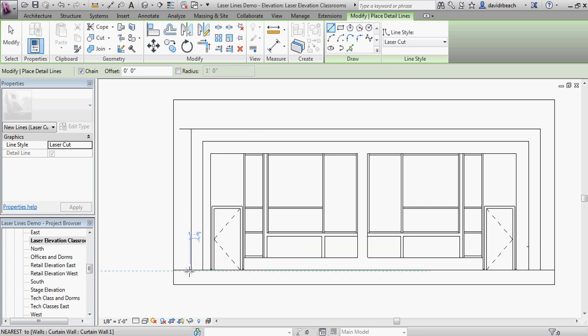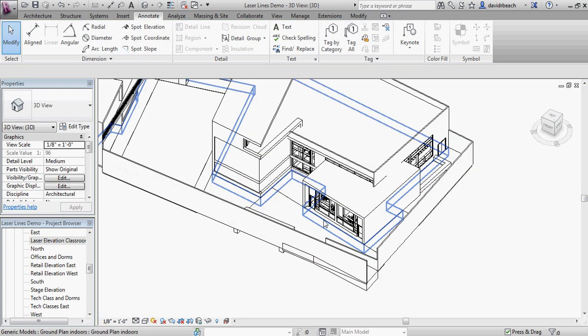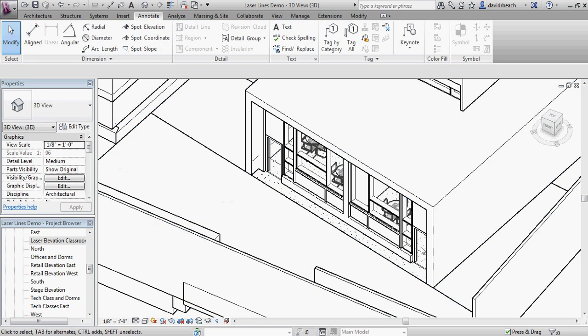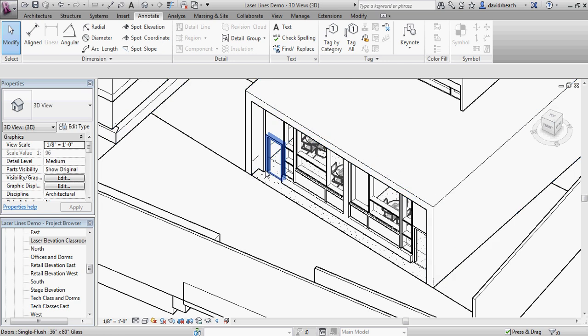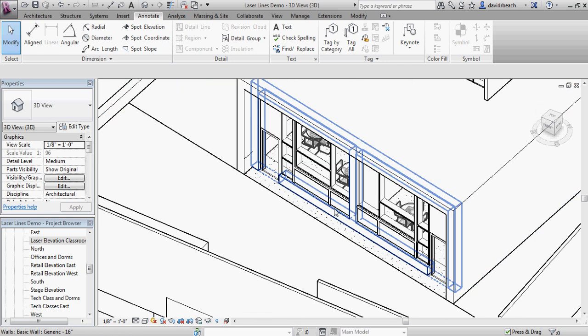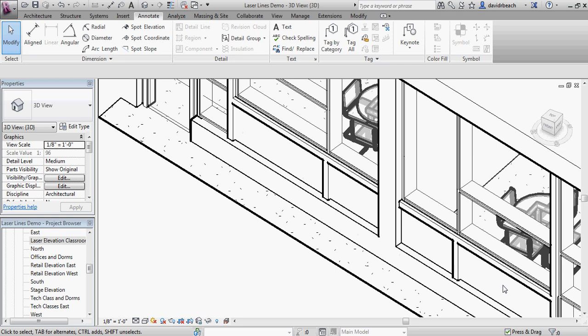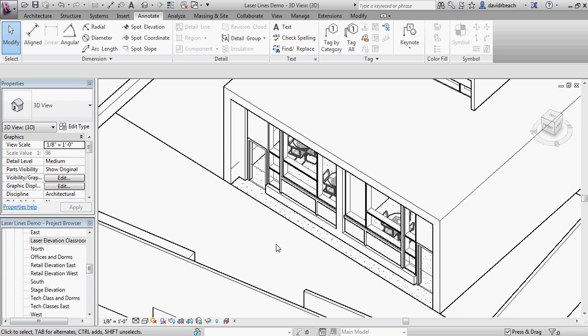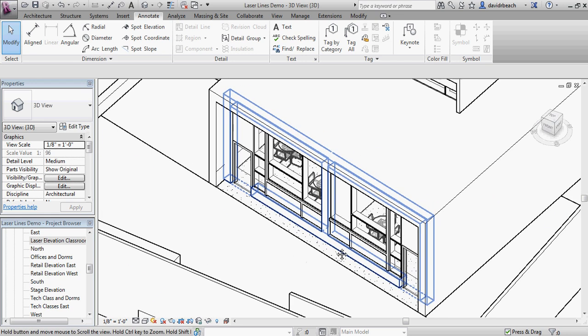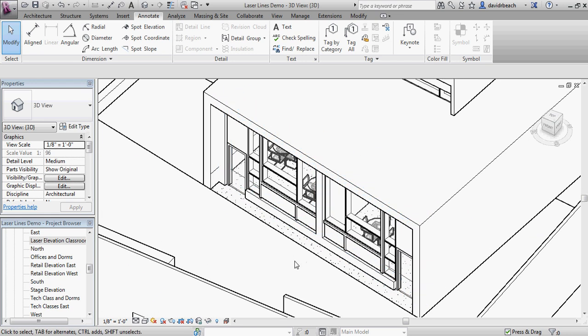So first thing I'm going to do is trace this outer edge. And again, let's look back at the 3D model so you can see a little bit of what I'm wanting to do. I'm actually going to be building this outer edge first, and I'm only really building this piece of a facade. So ultimately I'm going to think about stacking layers of chipboard up to generate this, and then the next profile in, the next set of profiles in. These pieces right here are actually infill panels, which is a block and stucco with a stucco pattern on it. This is a project in Guadalajara, so we have really low-tech building methods, concrete block, concrete, and then custom built on-site windows and glazing.